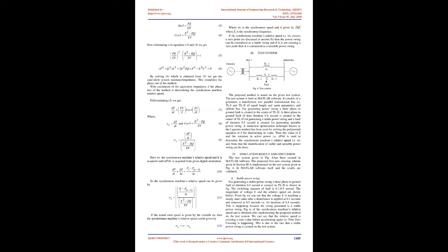Extensive studies of power system stability are not required for determining the distance relay setting. Unlike the traditional blinder scheme, this is the primary advantage of this method. The input quantities required for this method are simple electrical quantities that can be measured locally on the transmission line network. The paper is organized as follows.